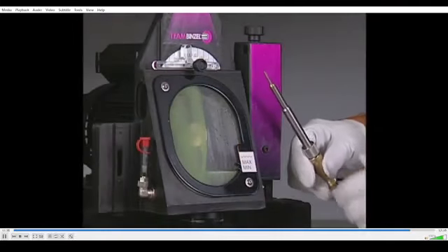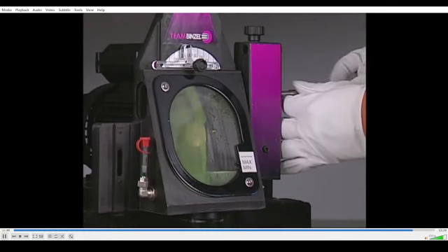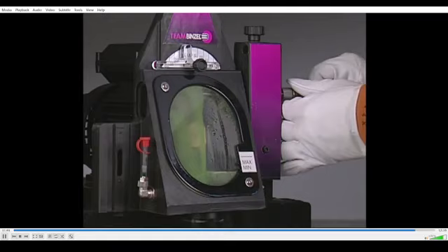There are a variety of tungsten grinders with diamond wheels on the market. Tungsten grinders are the best way to ensure precision grind because you can set them for the desired included angle and tip diameter.